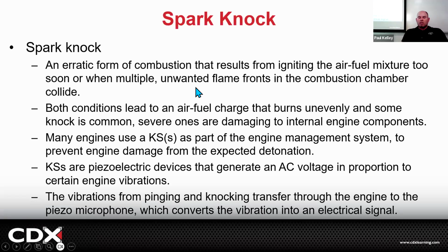Okay, so if this has spark knock, think of what that could mean. That could mean that the fuel and air is igniting prematurely, or that we have too high of a cylinder temperature or pressure. So why do you think that would be a concern? If we got the piston coming up, remember our timing? Piston comes up, spark occurs. We want it to occur maybe 10 degrees before top dead center so it can get a good power stroke. What if the combustion occurs too early? Oh, it could start to push the piston down the wrong way.